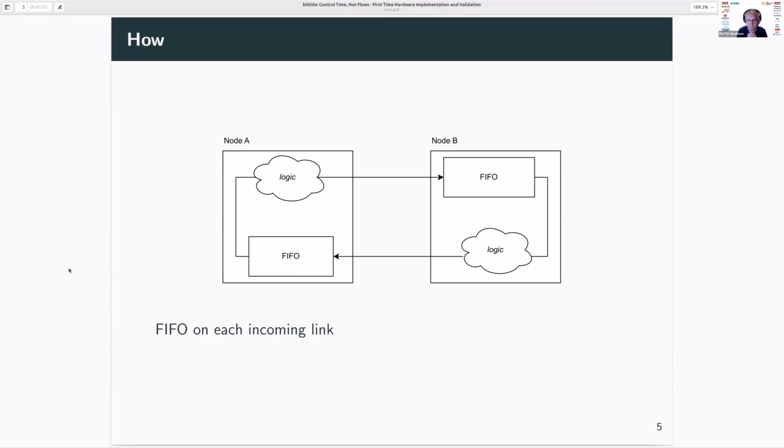What do we expect to happen in a running system? Well, not that much. Every time a node pops one item off the FIFO, another one gets placed at its rear end. This is a natural consequence of the definition I made in the beginning that these clock frequencies are the same.